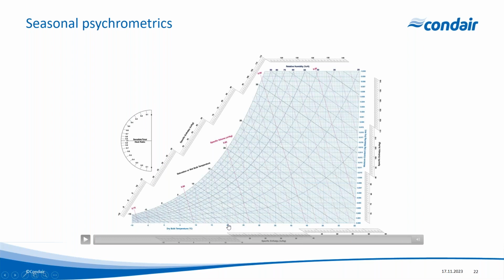So we know if we've got a dry bulb temperature of 20 degrees C and a wet bulb temperature of 14 degrees C, we can read from the chart that the relative humidity is 50% saturated. So there's 50% relative humidity, 60%, 70, 80, 90, and 100. So I can tell from those two temperatures what the relative humidity is.